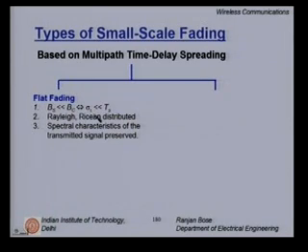Now, sigma subscript tau is only a function of the environment. It has nothing to do with the signal. So, if in a small room environment with lot of reflectors, sigma tau is much smaller than tau s, then in that case we will experience something called a frequency flat fading.